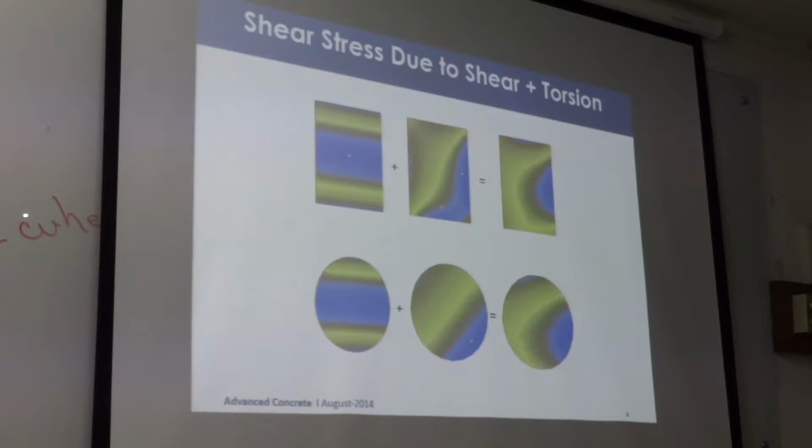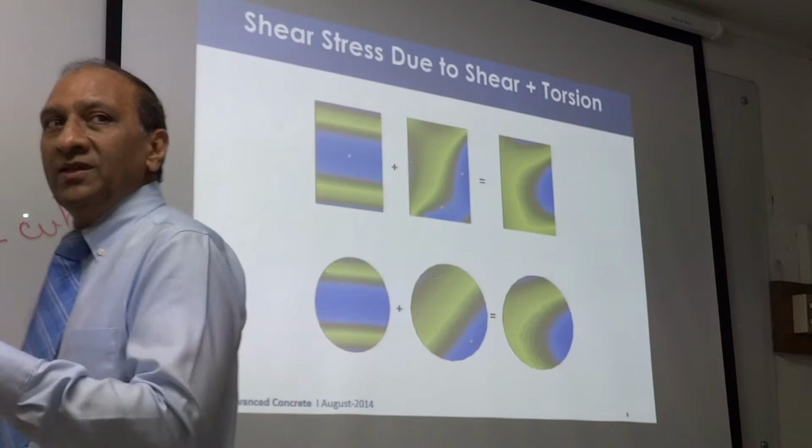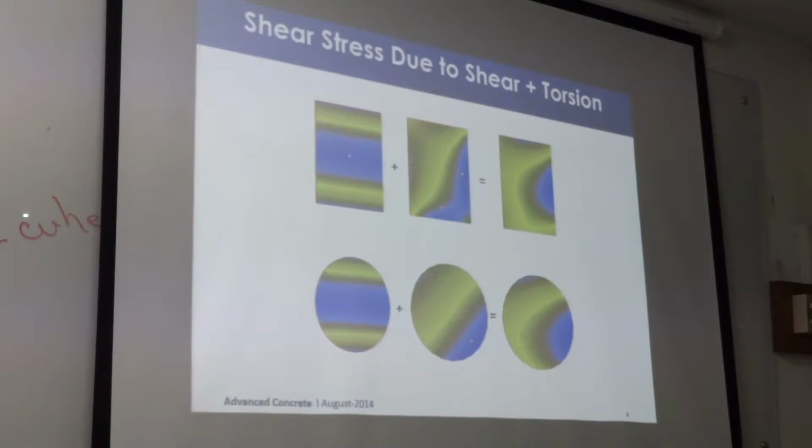And that is why we cannot use these theories completely for the shear design. We have to come up with something different than that. If it was just another material, steel would be fine. We could combine them, but we can't. Shear and torsion cannot be combined anymore, because in one direction it's already cracked, so the stress doesn't appear. It's cracking already. Stresses are gone, right? Because of the cracking. So you can't add them.